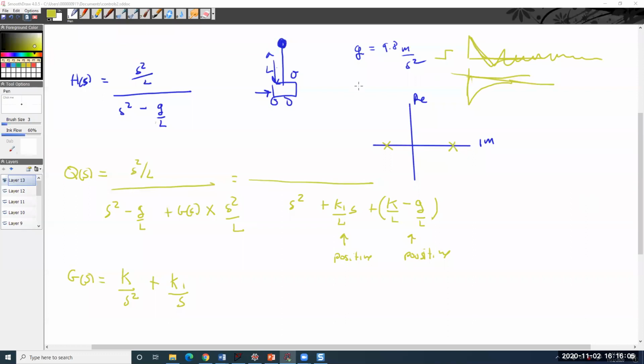Right, complex. So if I just have a set of complex poles here, and then I have a set here, and then I have a set here, this gets more and more. Complex poles means you're underdamped, right? But the closer you get, the more oscillations you'll get. And really, if you're right here, right on top of it, if it takes a day for your oscillations to stop, most people, that's not a good thing.